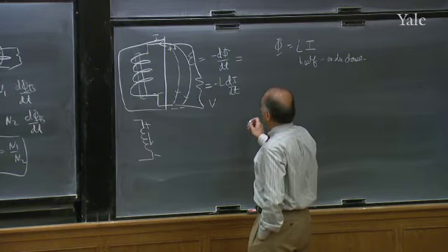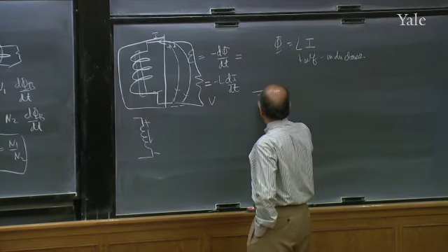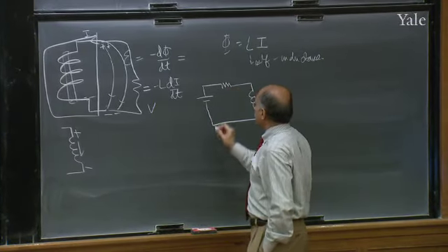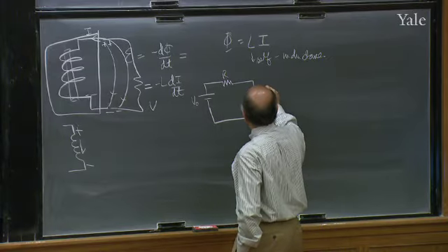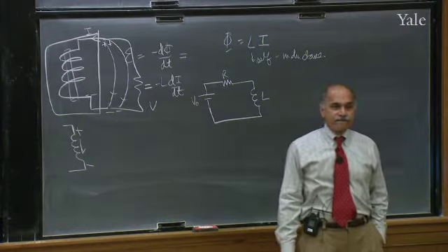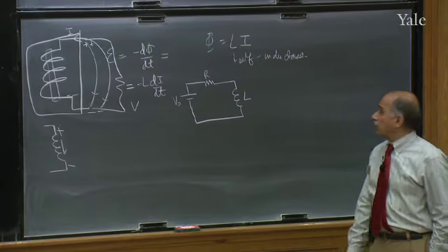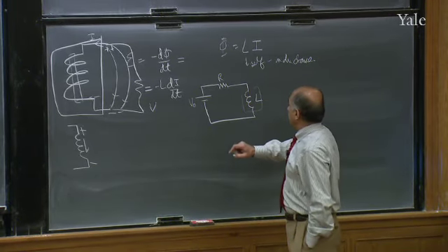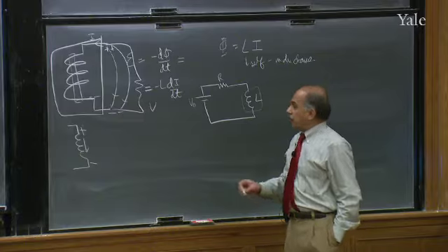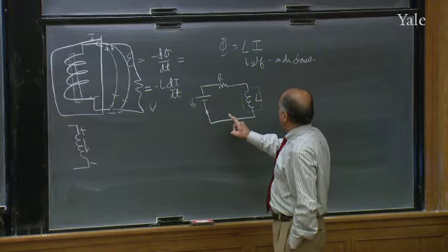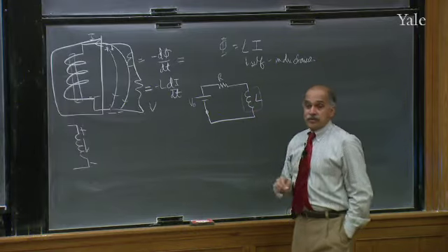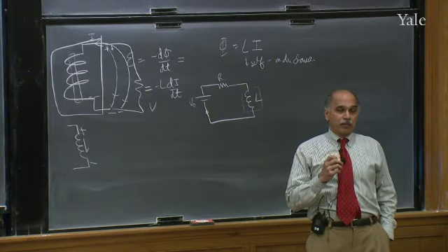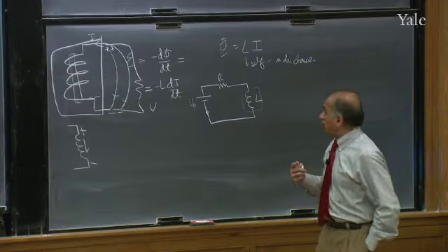So we can have the following very simple circuit. We have a battery here, we got a resistor there, and we have an inductor here. This is some voltage V, this is R, this is some L henries. So let us write a circuit equation, and here is where I spent an inordinate amount of time justifying what I'm about to do. I say start here. There's going to be voltage defined everywhere except inside the black box. You understand, you cannot define a voltage inside the black box where there's an inductor because there is a non-conservative electric field inside. But we promise not to go there.